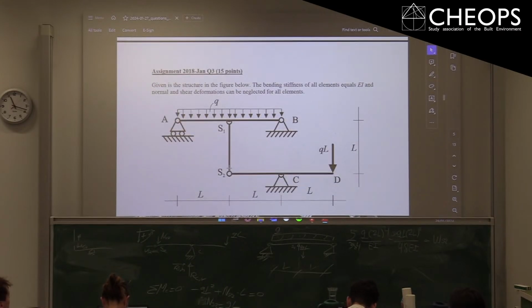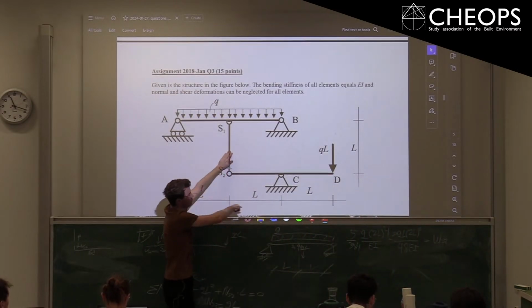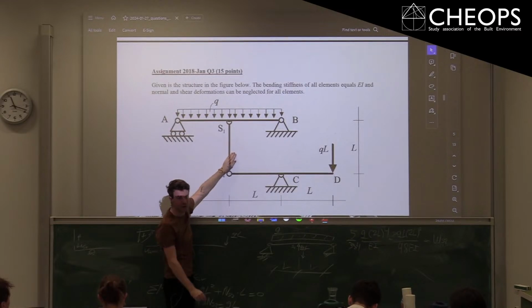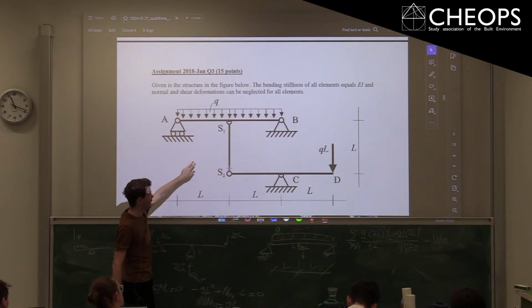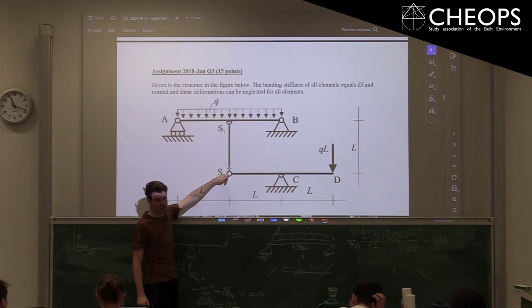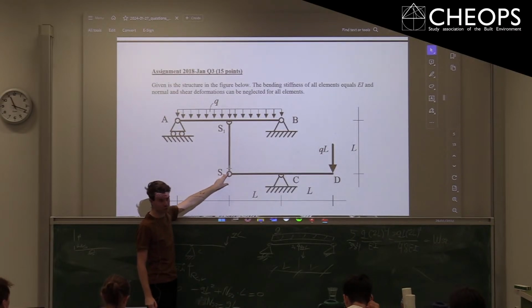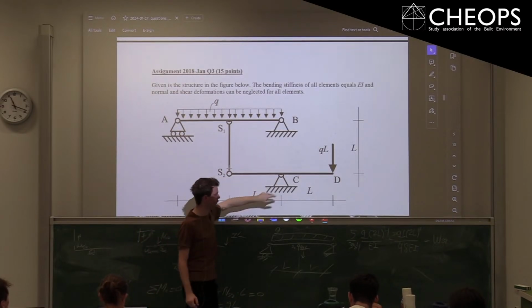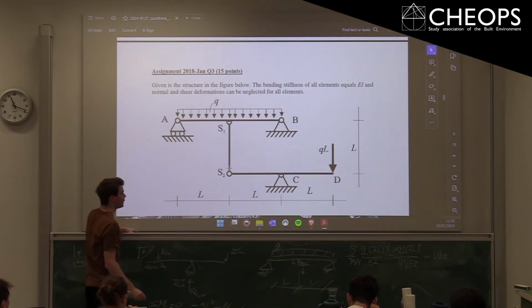And now we want to calculate point E, but if we use this bottom part as a free body diagram, we don't have standard beam equations for this, right? So you need to have a little bit of reasoning here. We know this one isn't moving vertically, so we're simply going to put this one as a roller support, right? And then you see that you have your standard beam equation once again.